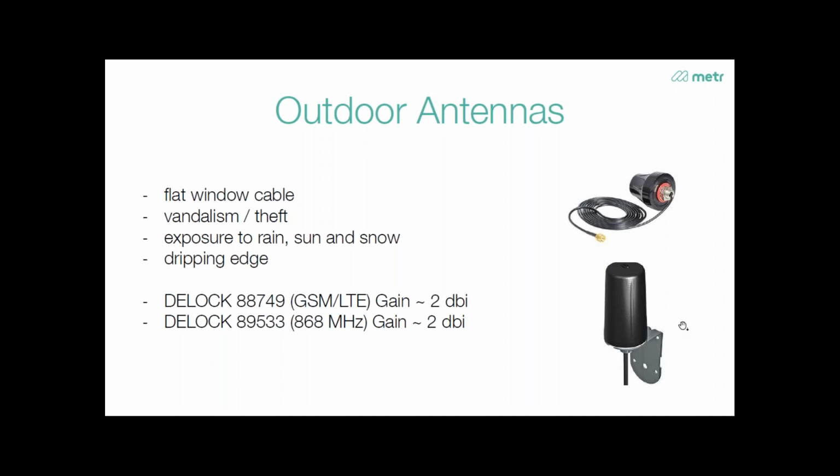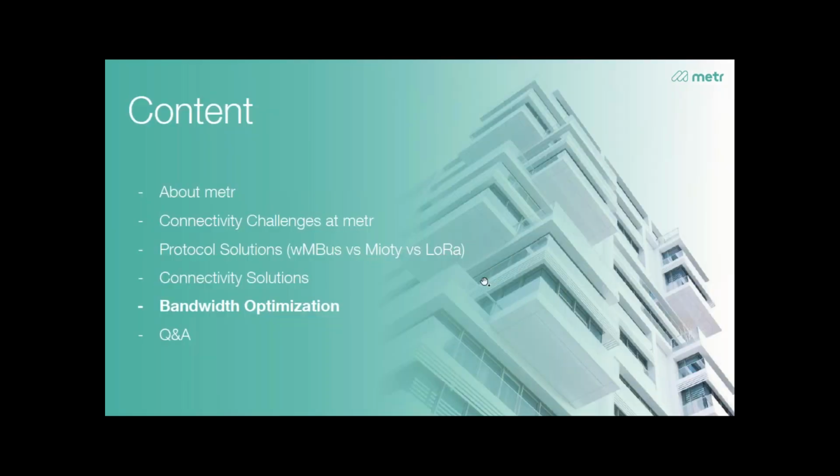So what you should think about is how to install it in a slightly inclined or tilted way, so the water doesn't get stuck there and can actually drip off. That's something you should really think about if you install an antenna outside. Most of the antennas that you can buy don't really provide that as standard. So, yeah, this is it for the antenna part.